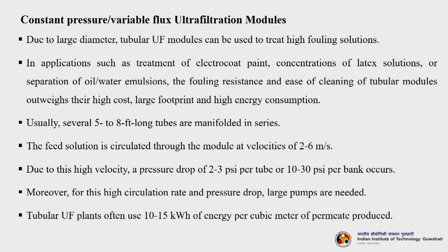It may need a little remineralization, but that is a different issue. If it is not so, then ultrafiltration also gives us ultra pure water, which may not be directly used for drinking water purposes, but can be used for other purposes. You can have a microfiltration membrane also. So, cost aside, we have to see what the intended application is, then you decide what type of membrane as well as module has to be considered.